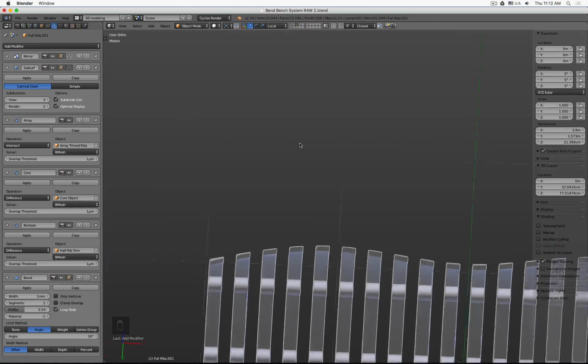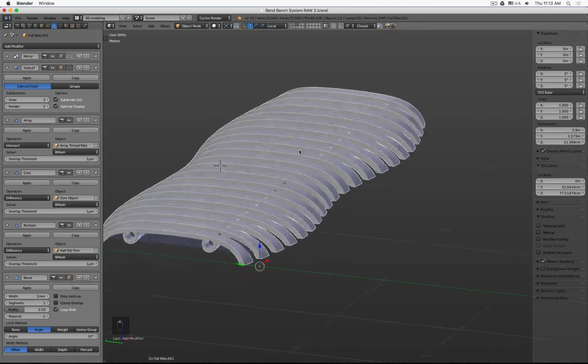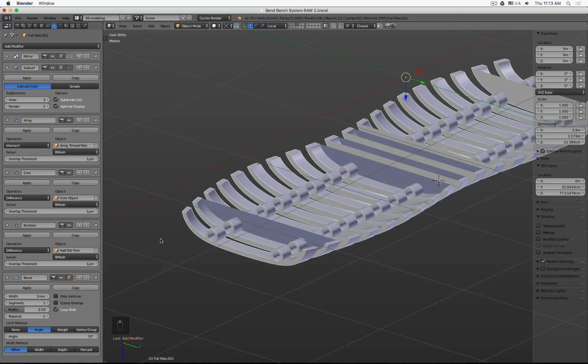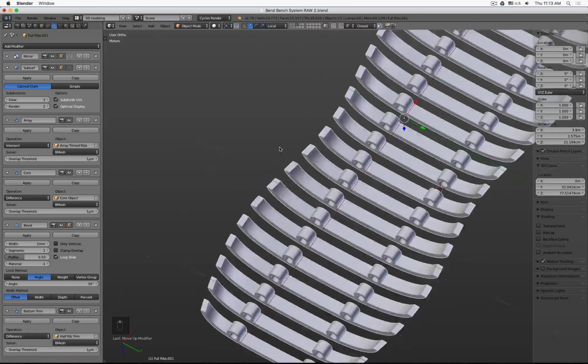And this is happening. Oh, this is interesting. So this is good this happened, because I can show you how to fix this. What you see there is basically the result where maybe somewhere 1 or 2 edges overlap, and then a certain command gets cranky. And this is probably due to the Boolean parts. This is actually, let's say here, the bottom trim. And I have my suspicion if I move the fillet up, this might fix it. Well, I was right. Perfect.